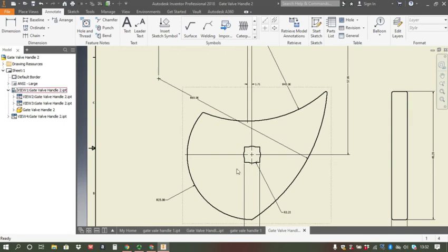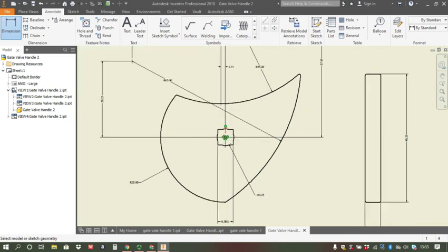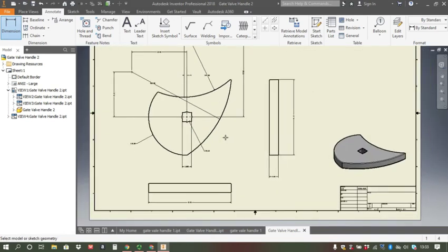Now I've checked that, I know how wide it is, I don't know how high it is, so I should really give it a height measurement as well. Oh, it helps if you press dimension. There to there. So now I know it's 29.12. Everything is referenced to this very centre, so it's easy to find. Yeah, we have one datum point.